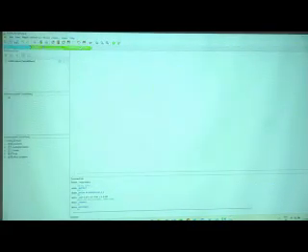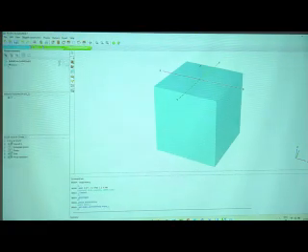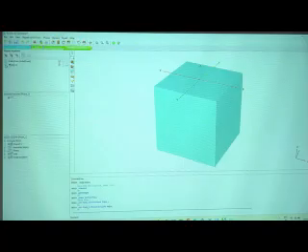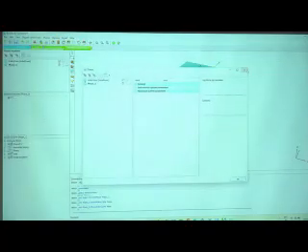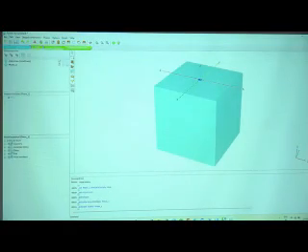After meshing, now how to apply the load? Like Abaqus, first the geostatic load was applied, then the gravitational load, then the main load. Similarly, we will use the same steps here. Like phase 1, I will go for embedded beams and plates.